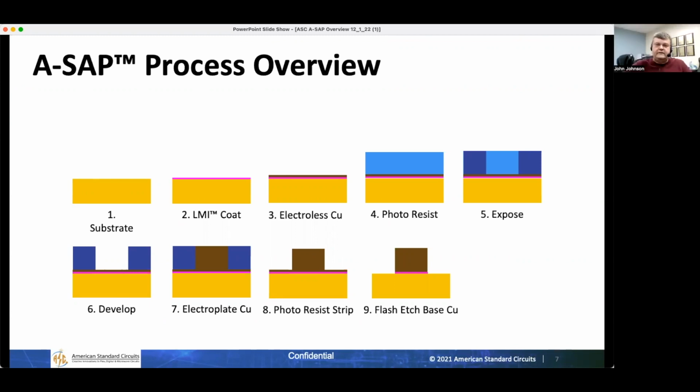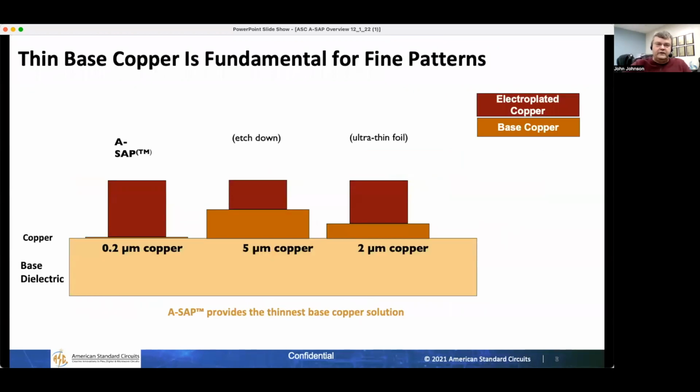Yeah, pretty close. In fact, I can show you some examples. Maybe I don't know if you have them in the slides, but we put this in at the Navy. They had been one of the early adopters, and in 2 weeks we were running panels there that had 25 micron lines and space. They had the capability with their photolithography to get down farther, and within another few weeks after that, we were running 12.5 micron, half mil lines and space.